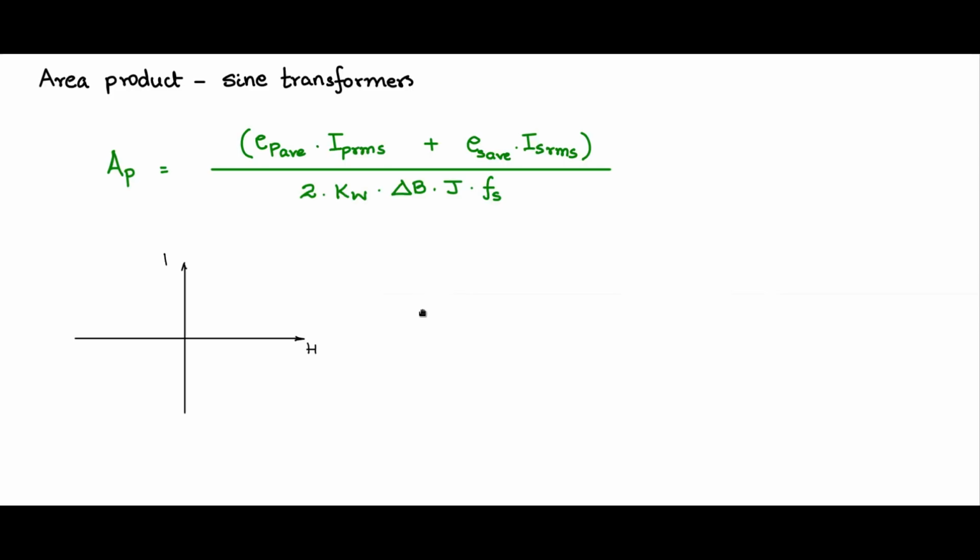If you take the BH characteristic, let me say a typical BH characteristic is something like this. This is plus BSAT, minus BSAT, and let us say the flux in the transformer core swings from a positive BM value to a negative BM value, minus BM. For every cycle it will go from minus BM to plus BM and then back to minus BM, which means in TS by 2, half the cycle, it would have traversed minus BM to plus BM or plus BM to minus BM.